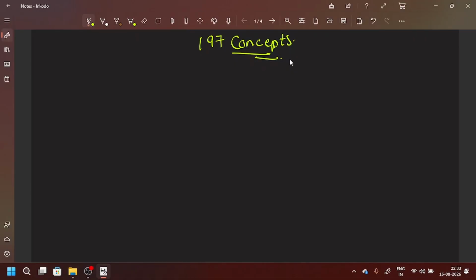trigger the initial values. So definitely we know that an RC phase shift oscillator or any kind of oscillator will give an output or oscillations without giving any kind of trigger inputs. Okay, so here Proteus is not able to do the minute simulations. It will consider the very minute noise signals as zero in order to get a clear output. The tool has been programmed in that way. So for that, instead of using a BJT or bipolar junction transistor, we will be using an op amp.